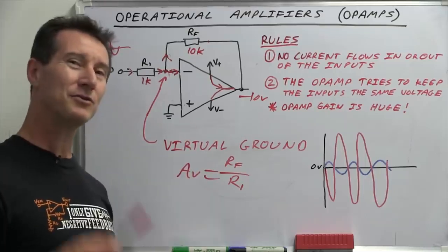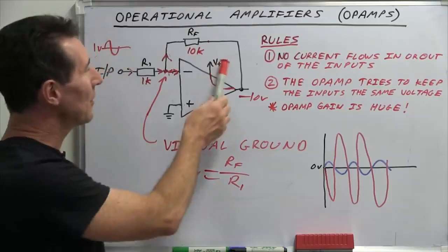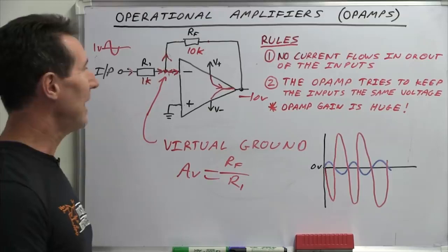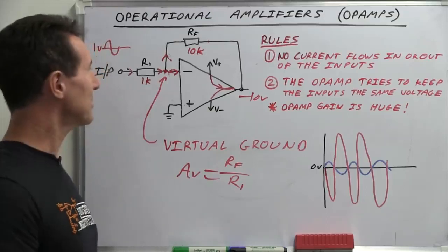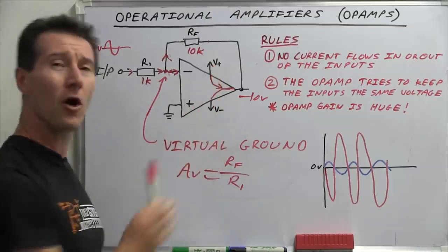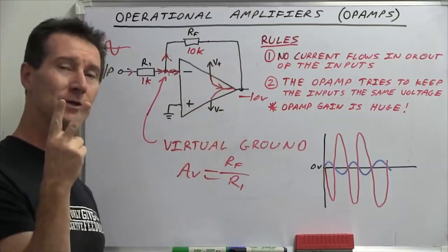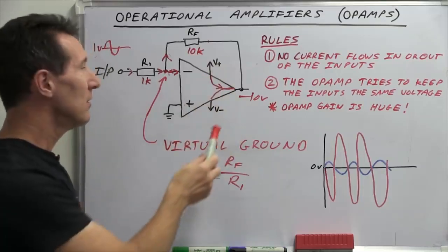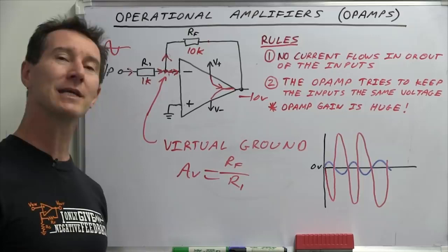Now we have to go deeper into this and talk about the power supplies and split rails and all this sort of stuff, and single supply op amps. I'll try and keep it as brief as possible, but you saw in this configuration the op amp only has 2 power pins. It's usually called V plus and V minus. Now V minus, you can actually connect that to ground.